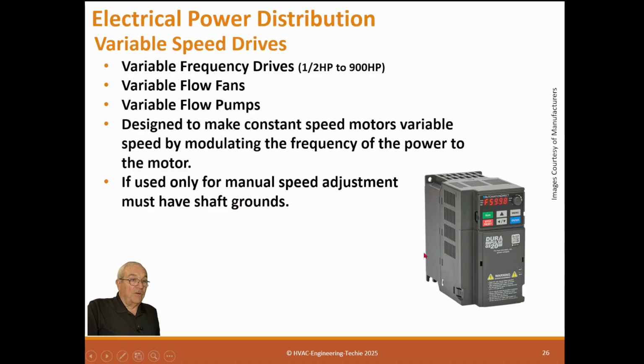So we've learned that by experience. Shaft grounds, you really should have a shaft ground on every single VFD motor. They don't always have it, but that's what they should have. Available for 1, 2, or 3-phase motors.